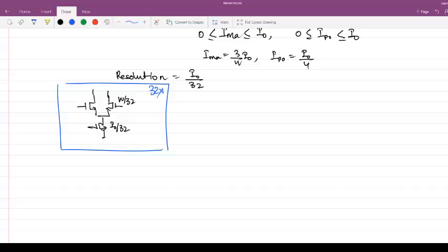So okay, if you do not scale the differential pair, and only scale the current source, your differential pair will be designed for the maximum current, so that it should be able to carry the maximum current. Now think that the post cursor is working with only minimum current, just for example, I naught by 32, and the main cursor is working with 31 times I naught by 32. In that case, the input pair for the post cursor is working with a different VDS than the input pair for the main cursor. Okay, this will introduce data dependency at the transition points.